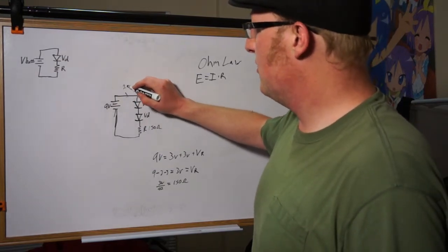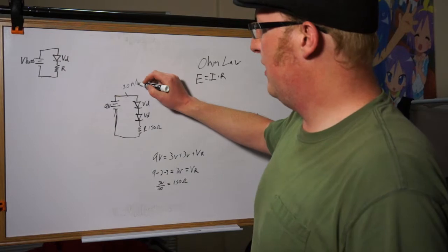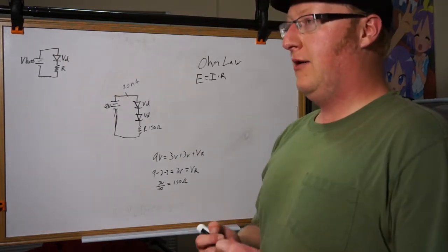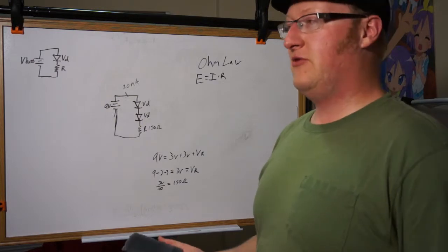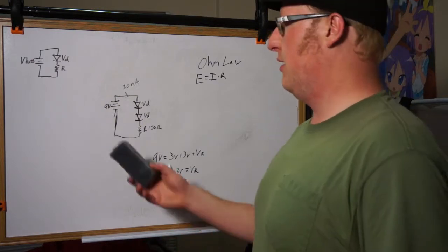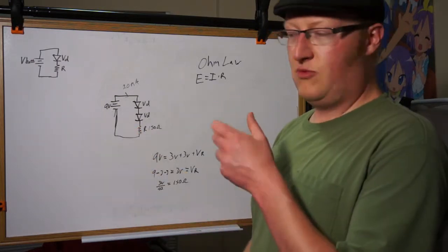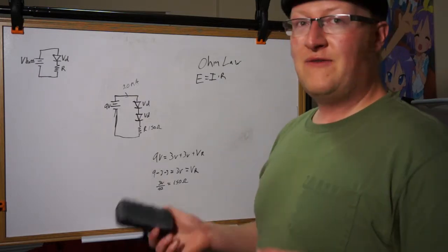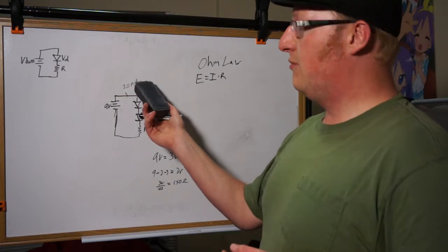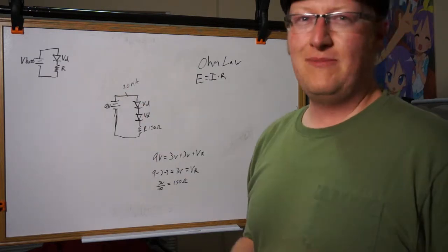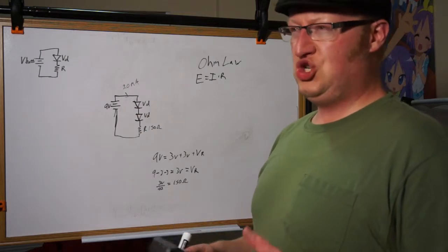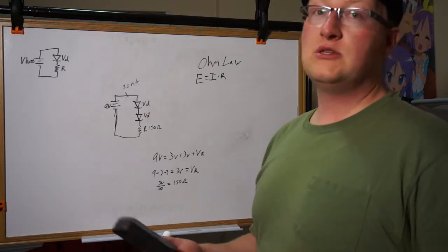It's worth noting that a battery essentially is rated in a number of milliampere hours. It's how many hours it can operate given the draw of that many milliamperes. If you draw less than that, so for example, 9 volt batteries, the standard rectangular cells are typically about 500 milliampere hour. So you take this 500 milliampere hour and you draw 20 milliamperes out of it, yeah, we'll call it 400 milliamperes to make the math easy. It essentially means that now that we're going to run for just about 20 hours.